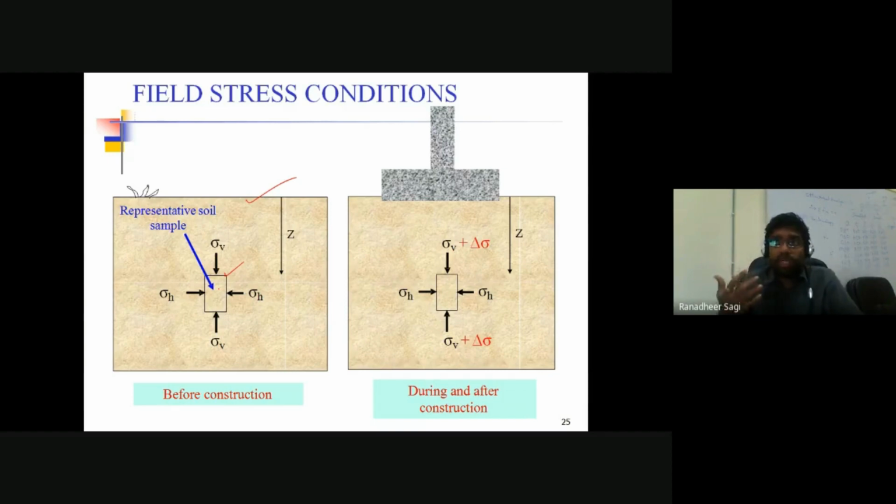Now, what could be the maximum increment in stress that you can induce in that particular soil before it is said to be undergoing failure? If I want to understand the maximum stress that I can transfer onto that soil in the form of superstructural load or any other additional load, then for knowing that, I should know the c and phi parameters of that soil.